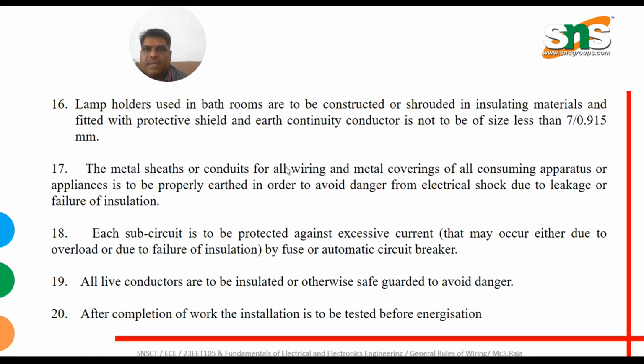Lamp holders used in bathrooms are to be constructed or shrouded in insulating materials and fitted with a protective shield, and the earth continuity conductor is not to be smaller than the size of 7/0.915 millimeter. The metal sheath or conduits for all wiring and metal coverings of all consuming apparatus or appliances are to be properly earthed in order to avoid danger from electrical shock due to leakage or failure of installation.